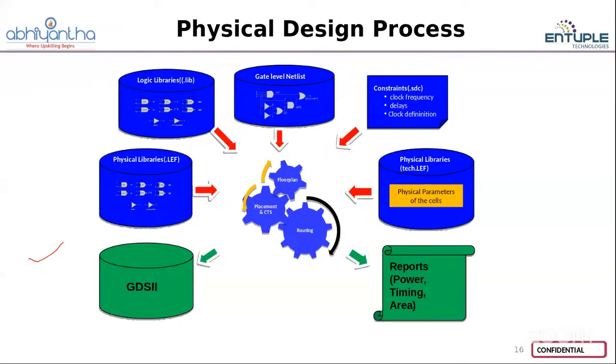Once all the steps are completed, we enter into the main stage called timing sign off. Here the timing sign off plays a very important role for timing optimization. For doing this timing optimization, we need to add all library files, that is the min, max and typical files.